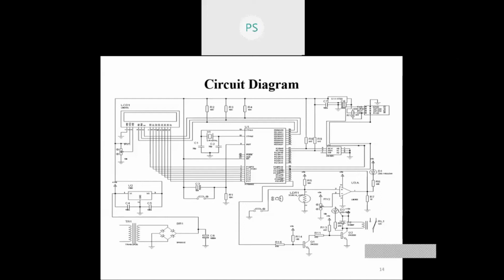If any I/O pin of port 0 is used in the circuit, then external pull-up must be added. As we are using port 0.1, 0.0, and 0.2 to provide RS, RW, and EN signals of the LCD, three 10K resistors, that is R2, R3, and R4, are connected from plus 5 volt to the I/O pins as pull-up. Port 0 of 8052 is open drain.